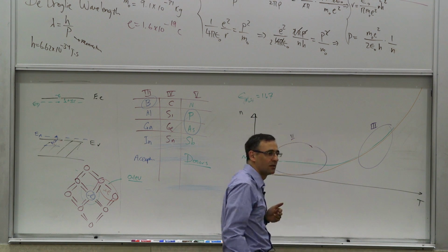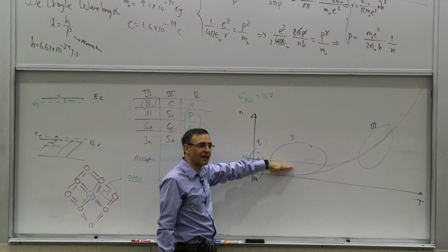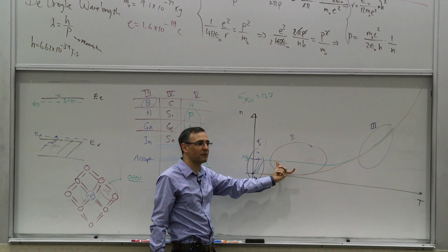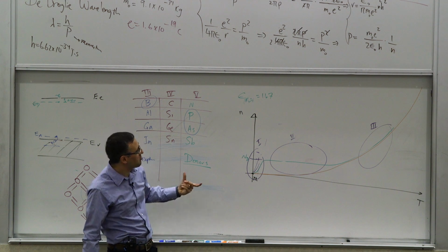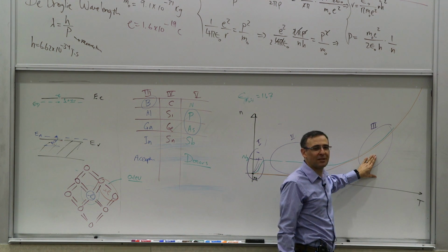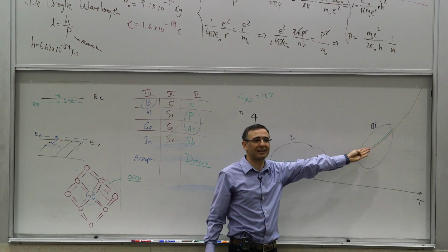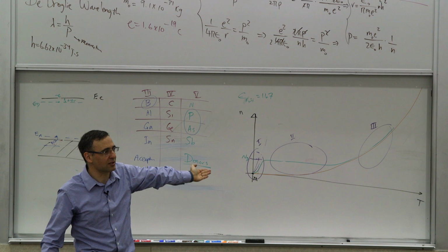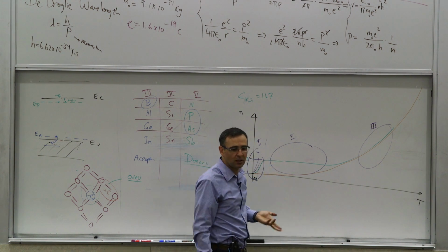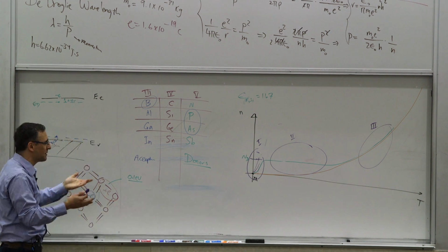What did you say region 2 is optimal for? Because the number of free carriers is well controlled and is stable, right? So you can control it by doping, and the number of free electrons that you have will remain stable in that region. And how about region 3? Is region 3 useful? I mean, as a well-controlled device, probably not, because now it's becoming what we call an intrinsic semiconductor. The doping is not doing anything, essentially. For all intents and purposes, doping is not there. So we want to operate in region 2, generally. If we can, region 1, there's ways of using it. You have to be careful. But generally speaking, you want to be in region 2.